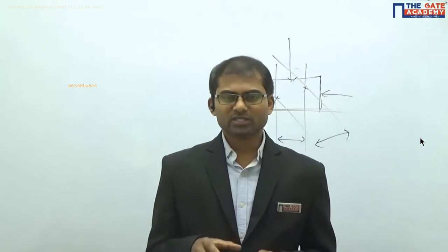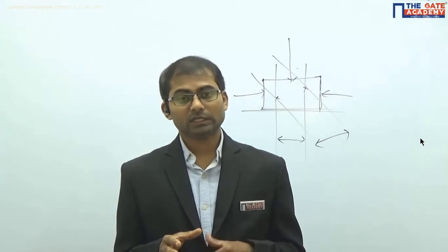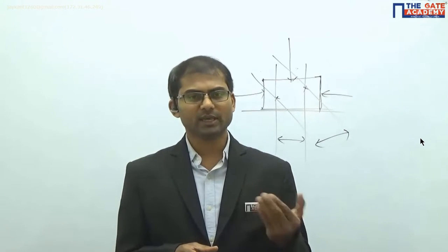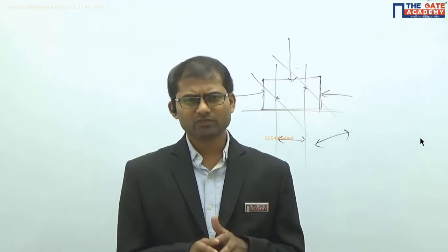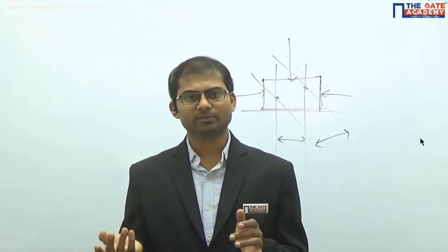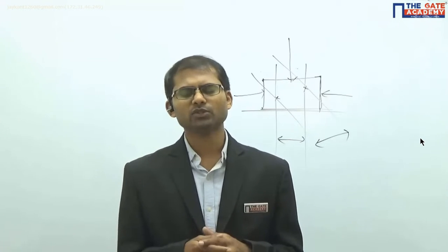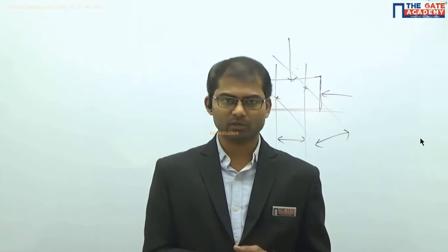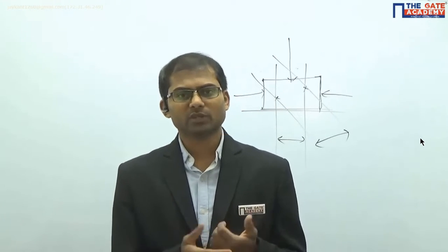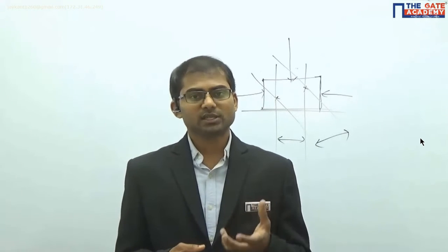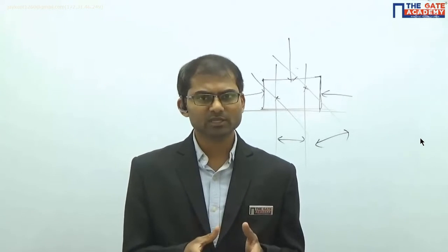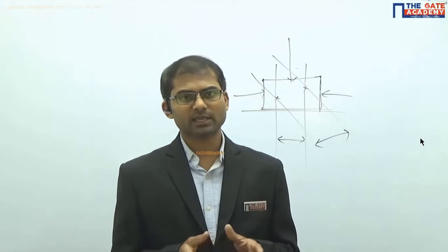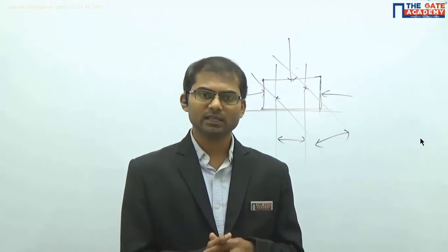So in this chapter we'll deal with loads which are static in nature. They act on the machine element and do not change their direction or magnitude with respect to time. Once we complete that part, we'll go to the second chapter, which is designing for dynamic loads. There we'll study how to do the designing for dynamic loads. Dynamic loads are the opposite of static loads, that is, loads which change their direction or magnitude, at least one of them, with respect to time. So we'll see static loading design in this chapter and dynamic loading design in the next chapter.